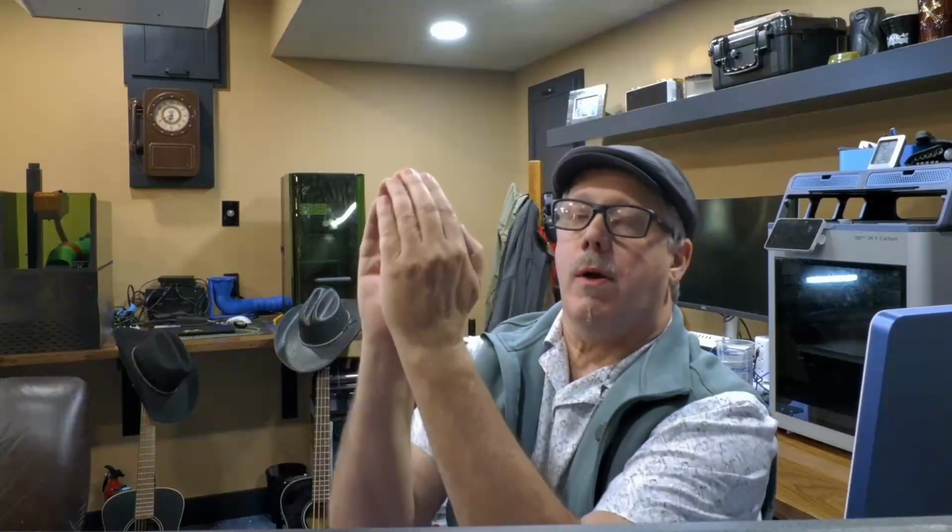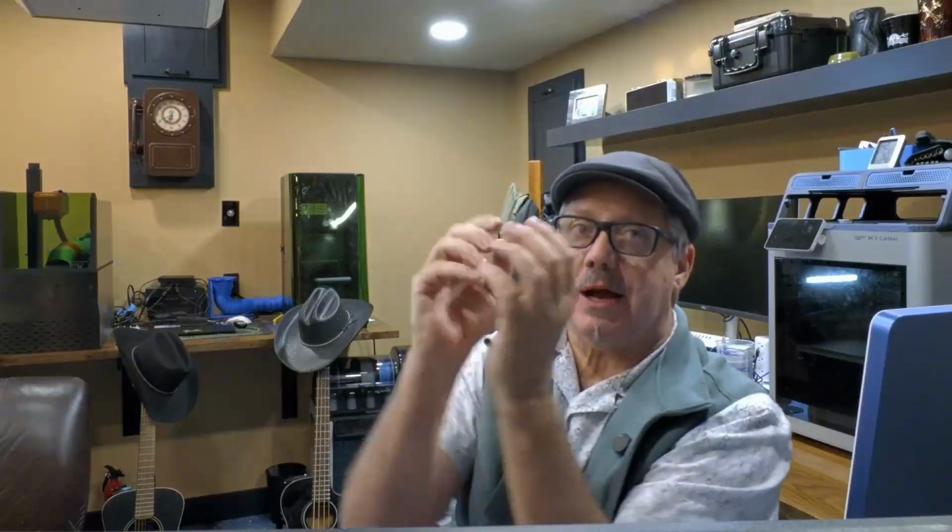and it's really small. But don't think of these, and you use round filament, so you think everything's round. It starts round and then it ends oblong. And we want to know how oblong it gets, right? How wide that gets when it squishes out like on a tube of toothpaste on your toothbrush. And is it a lot? Is it a little? Because the more it is, the more I have to design for those tolerances, right?